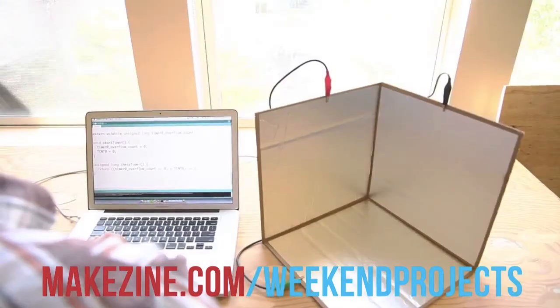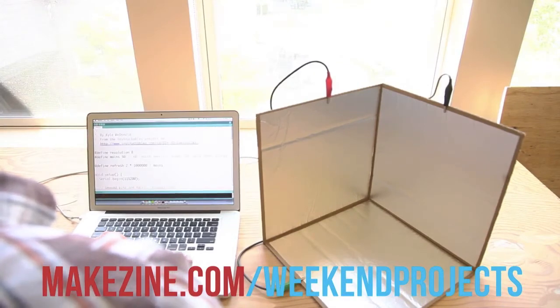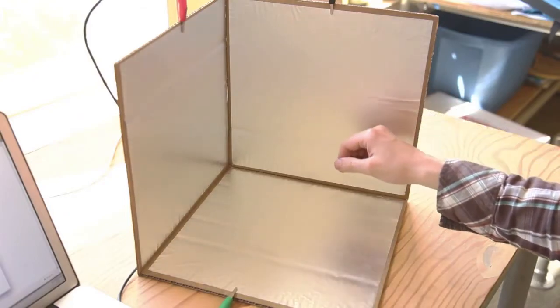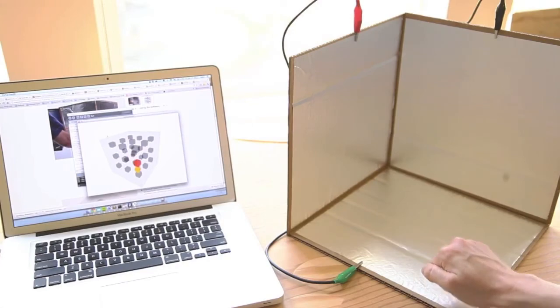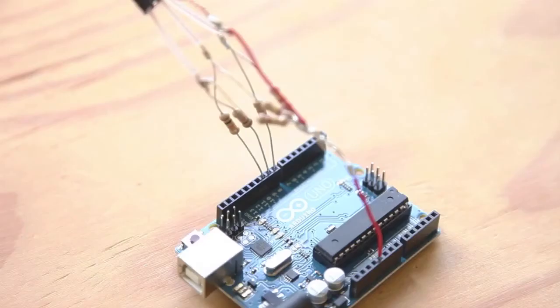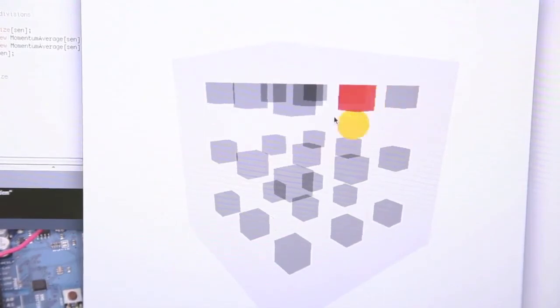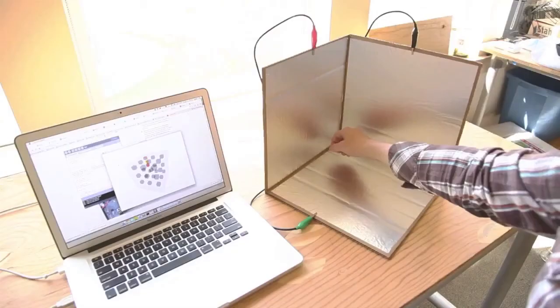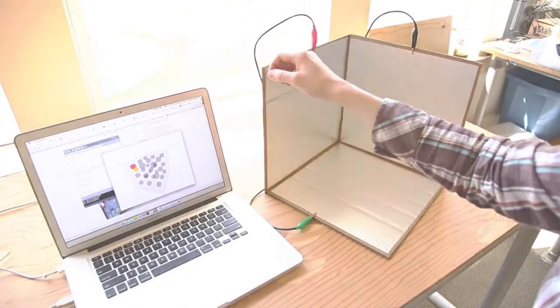From the Arduino IDE, upload the sketch to the Arduino. Keep the USB cable connected to the Arduino, then install and load the processing sketch. Now everything should be set. As you move your hand around inside the cube, the sphere should follow your movement. This project shows you one way you can use a microcontroller to turn very simple materials into capacitive sensors. The same techniques can be used to make your own touchscreens or turn pennies into switches. Try it, and you'll see how a simple idea can yield surprising results.